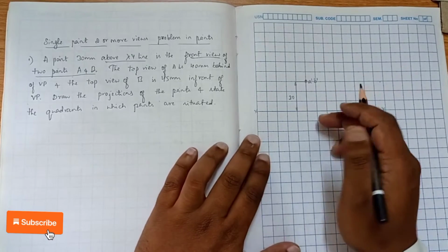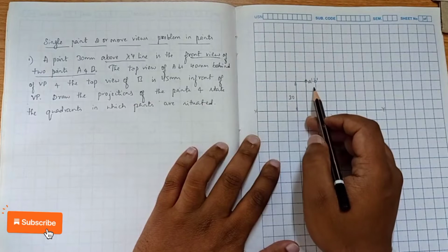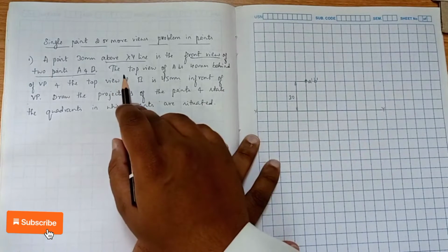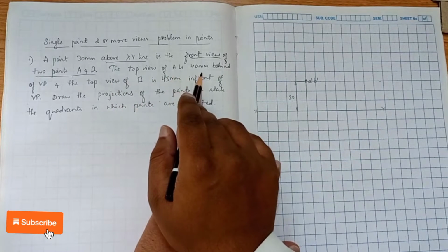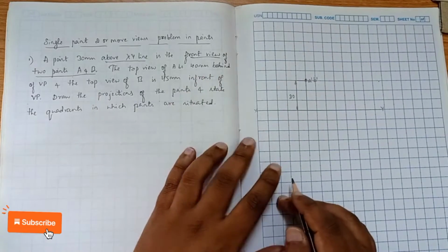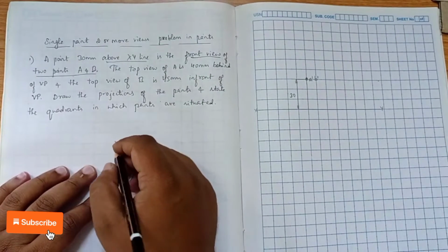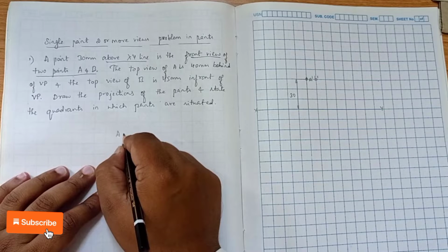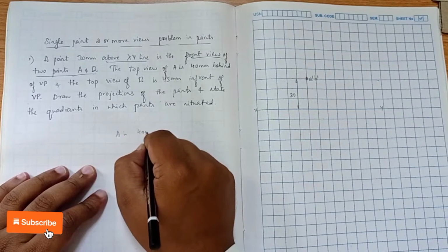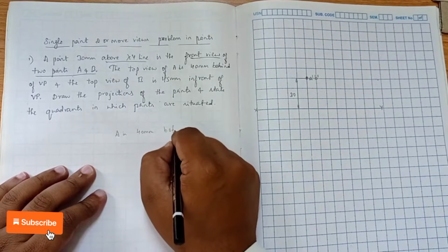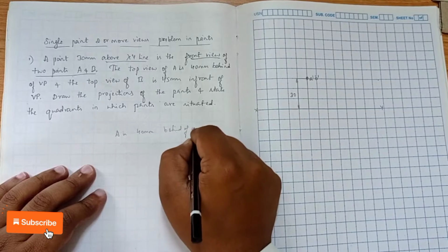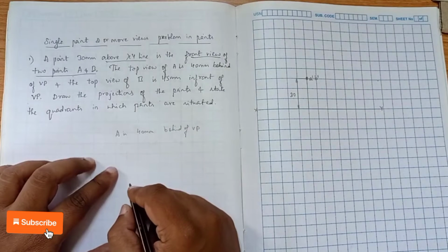We have done it. Now we have to see, this is the front view. Now we have to see the top view. The top view of A is 40 mm behind of VP. You can see the top view of A is 40 mm behind of VP. So behind of VP means,